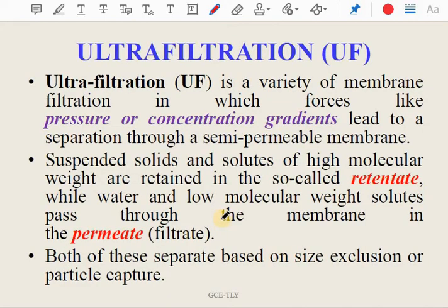Next is ultrafiltration. Ultrafiltration is a variety of membrane filtration in which forces like pressure or concentration gradient lead to separation through a semi-permeable membrane. The suspended solids and solutes of high molecular weight are retained, and this is called retentate or reject, while water and low molecular weight solutes which pass through the membrane are called permeate or filtrate. Both separate based on the size exclusion principle or particle capture principle.